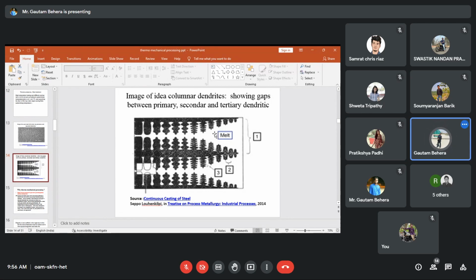And sometimes there are certain alloying elements which form carbides, nitrides, or carbonitrides, those are basically precipitates. So what will happen then? Or sometimes there are certain alloying elements which form intermetallic precipitates. Then what happens? You'll end up with intermetallic phases or precipitates in the interdendritic region, right? So obviously, what will happen? The material will be brittle. The solidified material or ingot will be brittle in nature because of these kind of things.